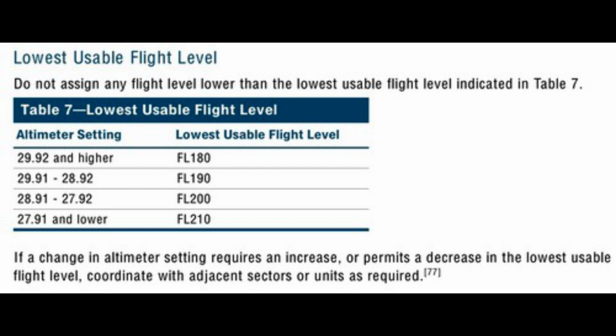When the barometric pressure exceeds 31.00 Hg, the following procedures are placed in effect by NOTAM defining the geographic area affected. Set 31.00 Hg for en route operations below 18,000 feet MSL and maintain this setting until beyond the affected area. ATC issues actual altimeter settings and advises pilots to set 31.00 Hg in their altimeter for en route operations below 18,000 feet MSL in affected areas.